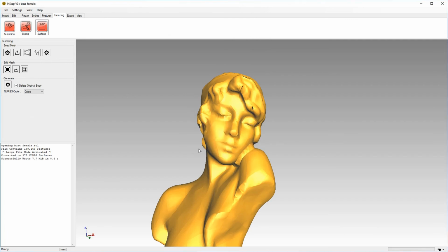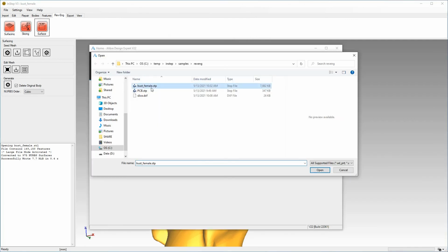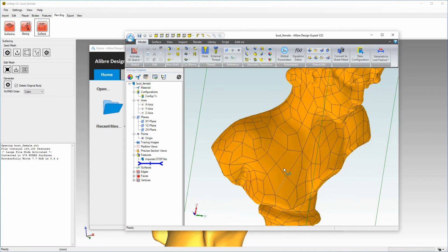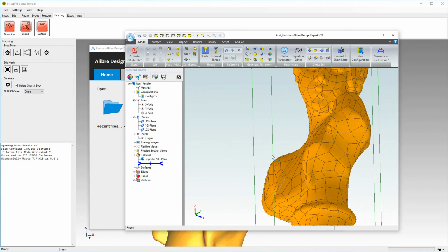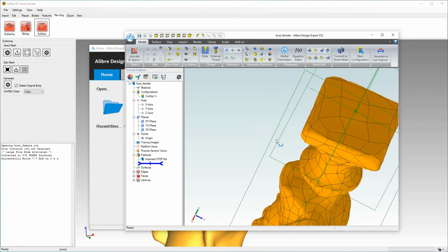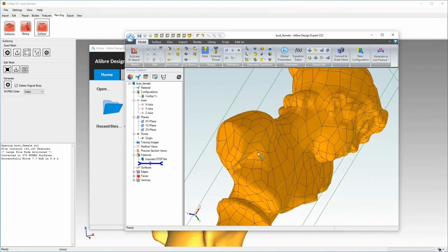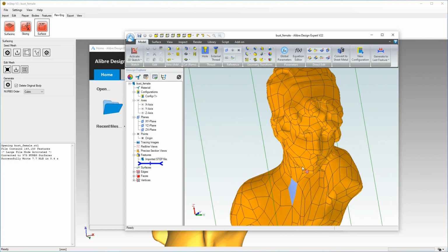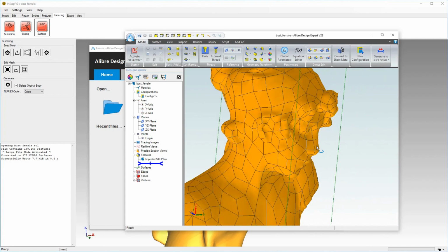We can use Alibre again to import this file. Now, after just a few minutes, the import will complete. However, it should be pointed out that there's often the chance that some errors will be encountered. If we take a closer look at that, that is often related to things such as overlapping surfaces or similar. So it may be necessary to go back in and make corrections, or make those corrections directly in your CAD application.